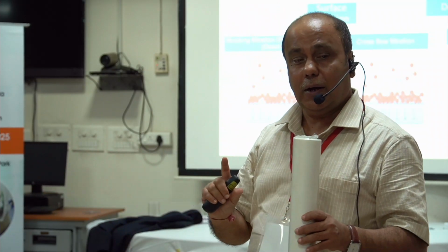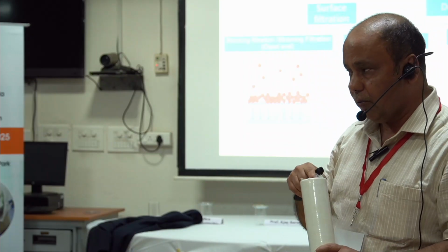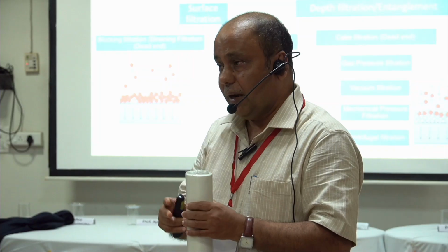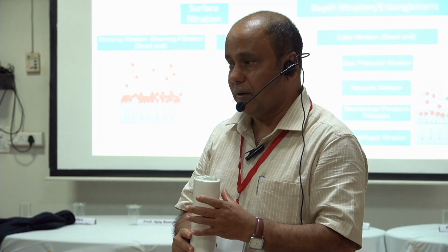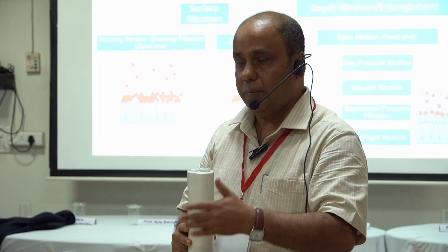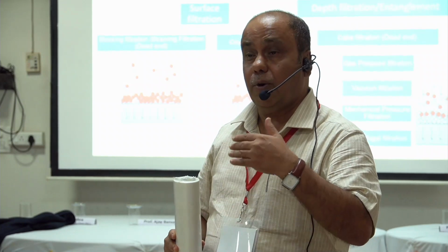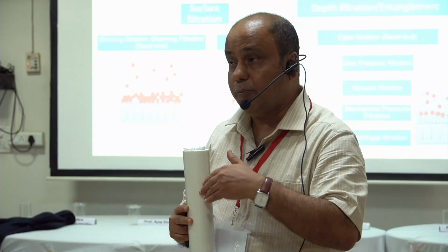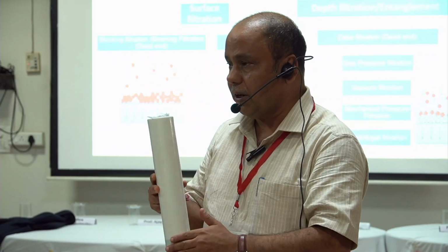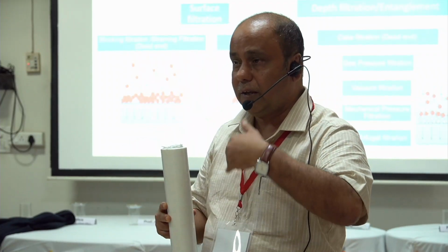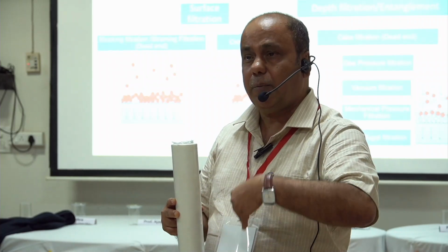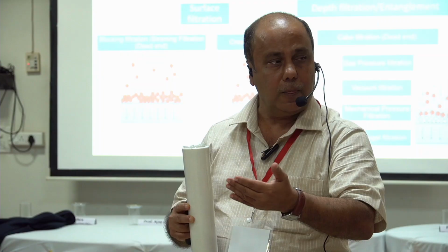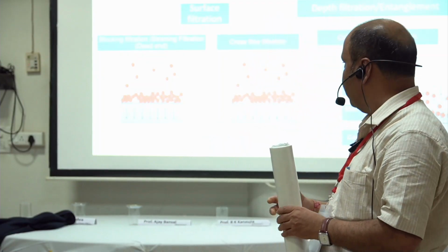Anyway, what I am trying to point out is that if it is going for a depth filter, you will get the benefit of energy, because unnecessarily you don't have to compact the material so that it can be deposited on the surface. And whenever you are going for surface filtration, cake filtration, we try to dispose of the cake that is deposited in the cycle. Disposing of means we are regenerating the material, so again it takes part in the filtration process.